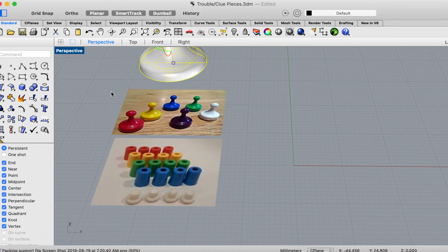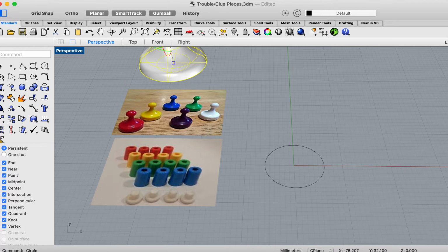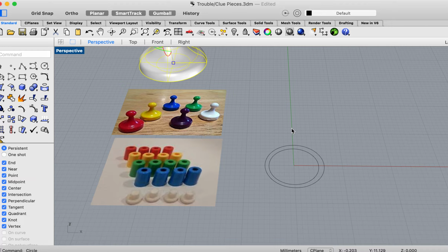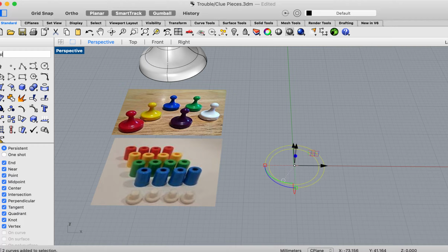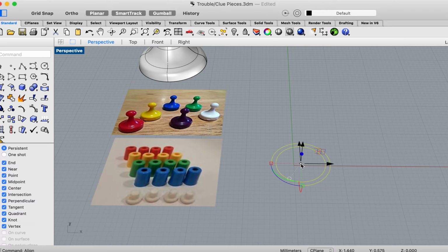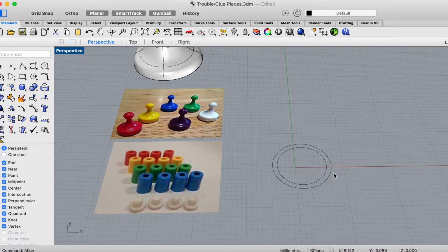Okay, so this is to create something called the loft function. I'm going to start by creating the bottom circle here, and I draw a single circle like that, and then I draw the inner circle, which is going to be the hole. Now, because it wasn't snapping to the grid, it's not aligned, so I'm just going to type a line, and I'm going to go concentric, and now those two circles are aligned.